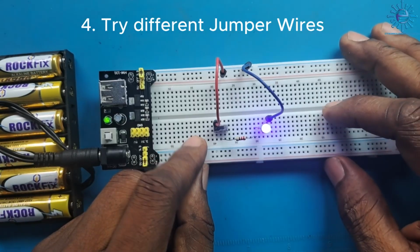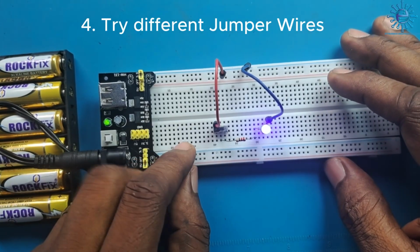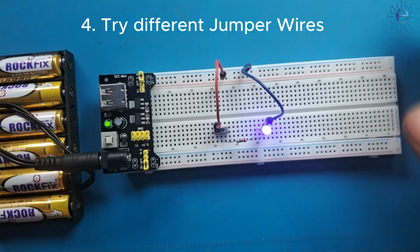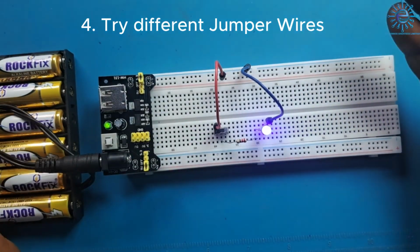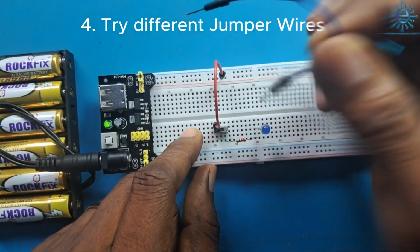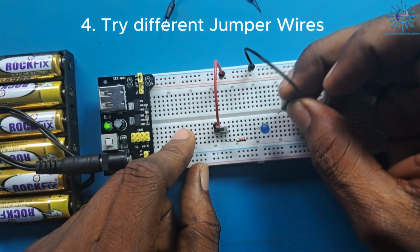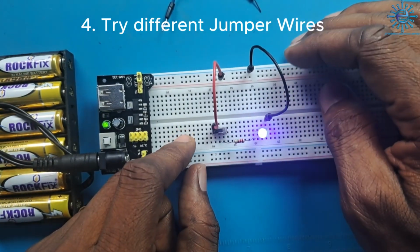Try different jumper wires. Sometimes a jumper wire may be damaged internally, even though it looks fine. Replacing jumper wires can help you identify and fix the problem. So if your project is not working as expected and you've tried some things and it is still not working, you can try changing the jumper wires, replacing them with other ones. If the problem is the jumper wires, then by replacing them, the circuit will start working.